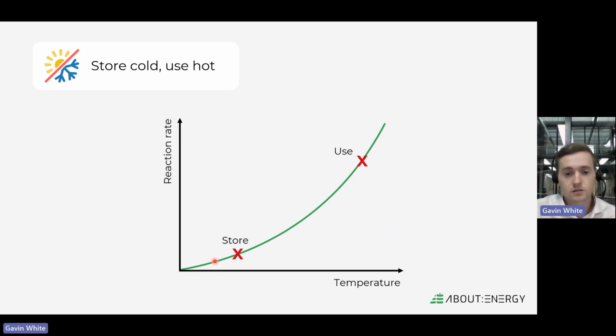When you're storing your battery, you don't want any chemical reactions happening. Those chemical reactions are side reactions degrading your battery. So you want to store it cold, where it's really unfavorable for these reactions to occur.